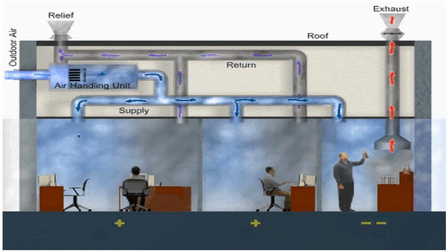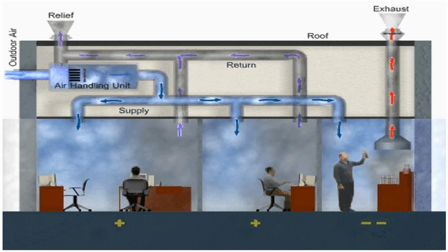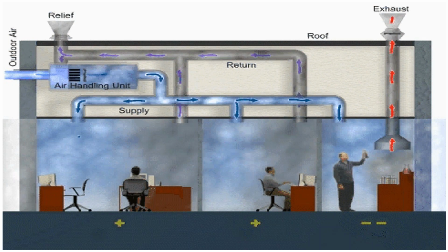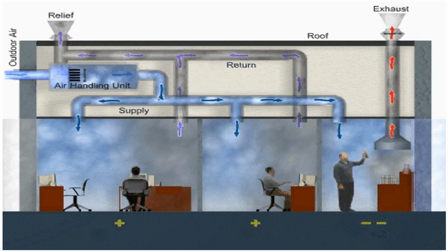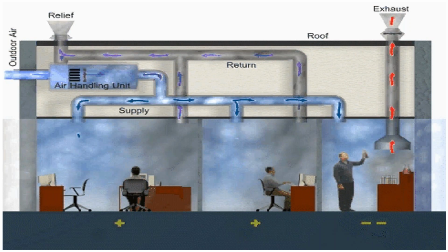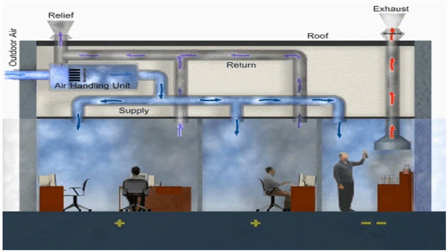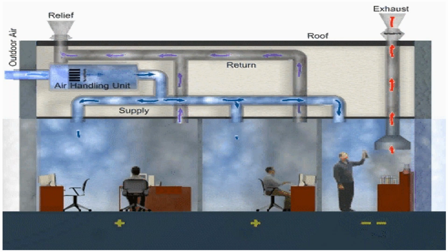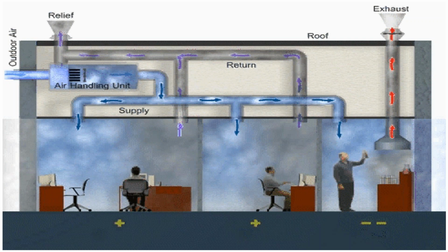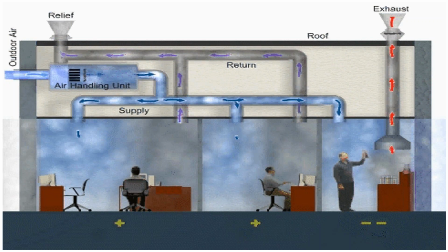So we need to make sure that we have good filters in place to be able to remove the particulate, which then gets sent into the workspace or again into the lab space. So then we have two choices. Now that the people in the room or the process in the room has contaminated, sorry, I'm north of the border, process. I can say it properly now. When you're inside the space and you contaminate the room, we have two choices. We can either take the air and dump it back outside, which could be a costly measure, especially if you have to heat, cool, humidify, and dehumidify it again, or we can recirculate it within the space, but we need to make sure that we're removing the contamination particles from that air.